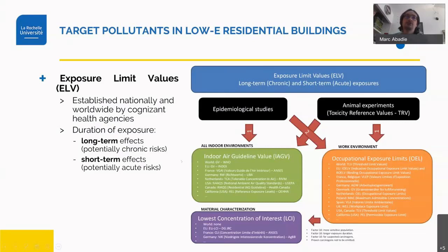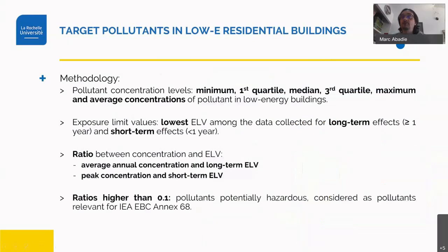So our methodology to define target pollutants was to use the data of the pollutant concentration levels I showed you before, and to use the exposure limit value database that we had. We chose to take the lowest exposure limit value for each pollutant, considering separately the long-term effect and the short-term effect. And we made a simple ratio of the concentration by the limit value.